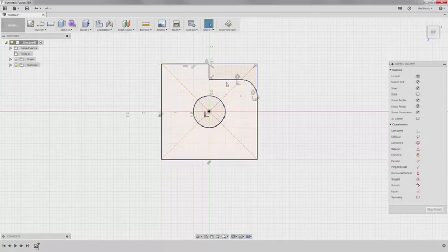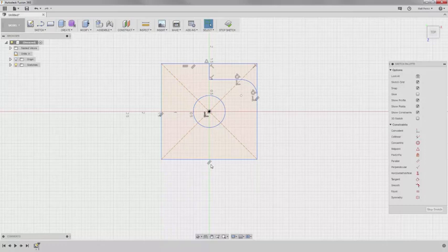tangent arc. There are icons that automatically appear in the sketch as constraints are automatically applied. The circle with the line signifies a tangent constraint. The icon shaped like an L signifies coincident constraint, and the 2 lines here signify a parallel constraint. If you hover over a constraint icon, it will highlight the entities connected by the constraint and any related icons. This icon shows a horizontal constraint was applied to one edge, and the others are either perpendicular or parallel.